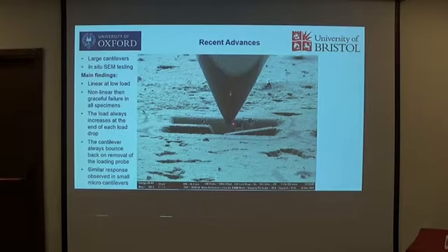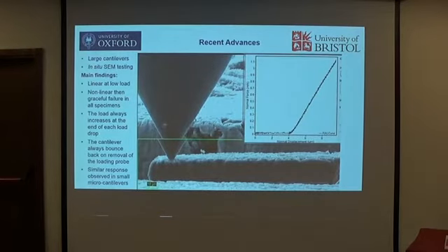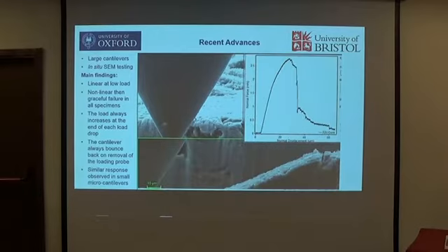The diamond tip is flat, and it breaks the cantilever. With this in situ testing, it loads up and you can see the deformation at the same time. The diamond has a flat tip, so it doesn't indent into the material. Most importantly, you can see the whole curve. The graphite is really quasi-brittle. It goes up linear, non-linear, then there's a fracture, and progressive fracture afterwards.